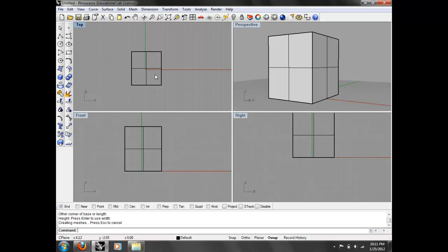The next thing I want to talk about is how to navigate the viewport. You guys know this from AutoCAD. You know, you can pan a drawing, you can zoom into a drawing. Okay, these are the things that you need to know how to do in Rhino. Zoom is the mouse wheel, in and out, okay? To pan, you want to use the shift.